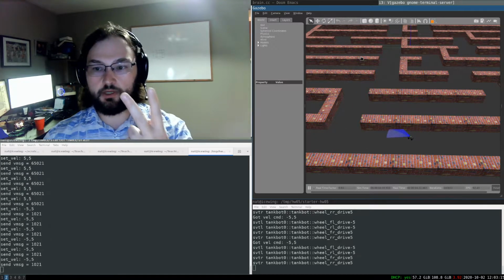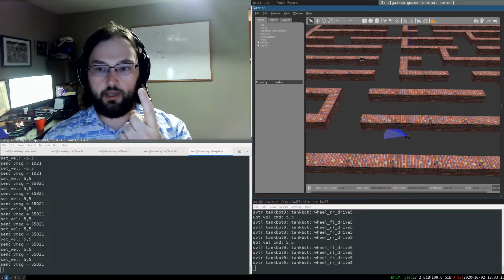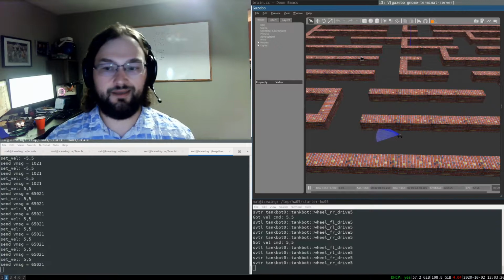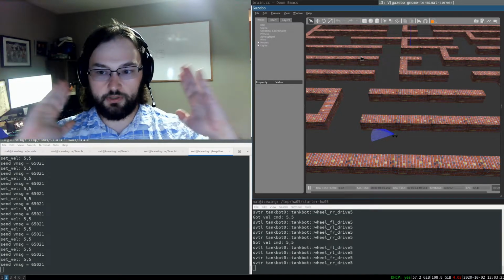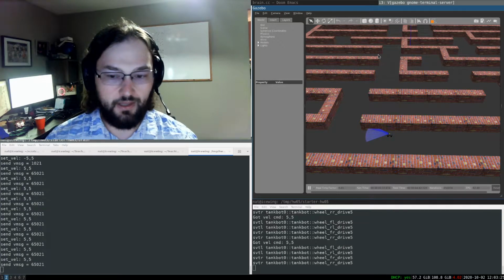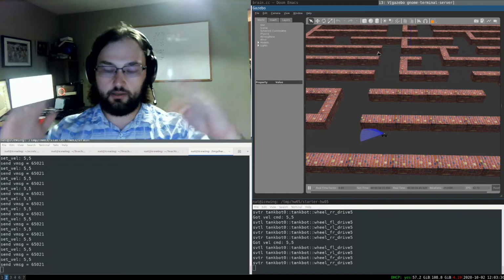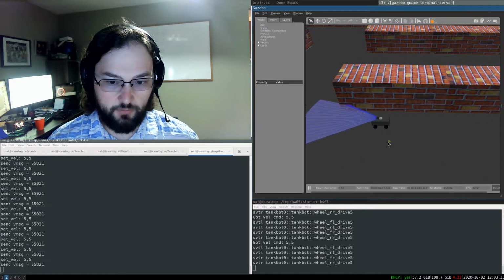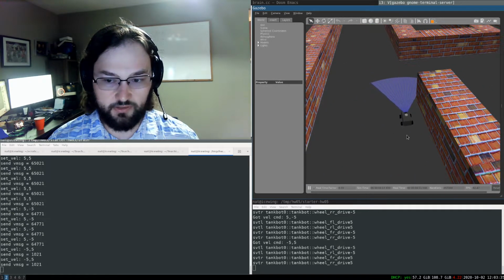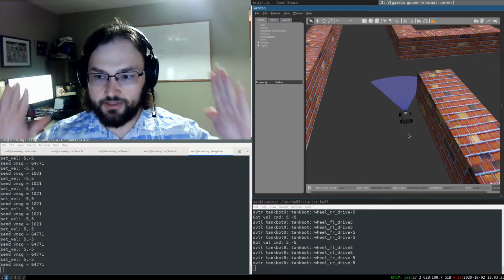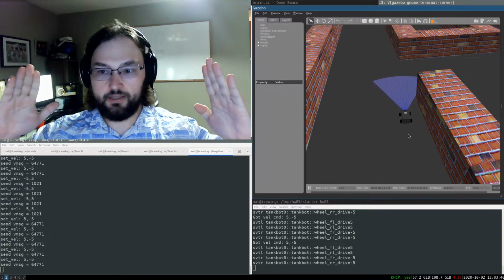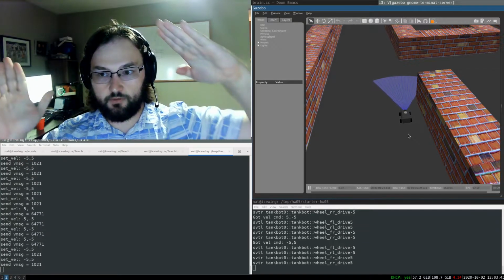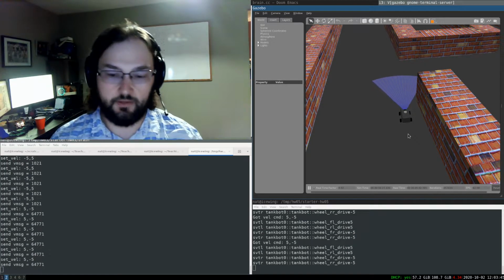Previously we had 2 different commands for robot motion. We had robot turn angle for the wheels, and then robot velocity, which was a forward-backward velocity. Here, instead of car steering, this robot does skid steering or tank steering, where we have separate control over the wheels on the left side and the wheels on the right side. Conceptually, if the wheels on one side go faster than the other, we can be moving forward, and we turn away from the side that's going faster.